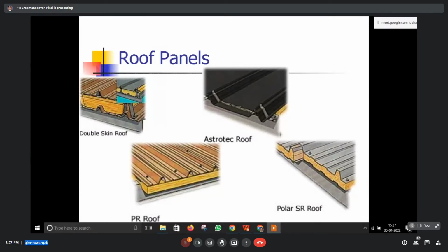So I went there and I was inspecting the material around. We think that steel will be highly conducting, a heat conductor, but I saw that the construction technique used is 2 steel sheets with polyurethane foam pressed in between them. That is used for the wall of the cold storage. Very lightweight, very cost economic, and the conductance is almost nil. That is why I'm saying there are so many such materials.